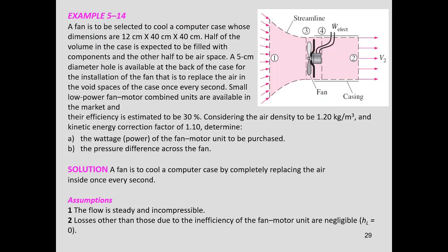A 5 cm diameter hole is available at the back of the case. So here, the dimension is a 5 cm hole, at the back of the case, for the installation of the fan that is to replace the air in the void space of the case once every second.